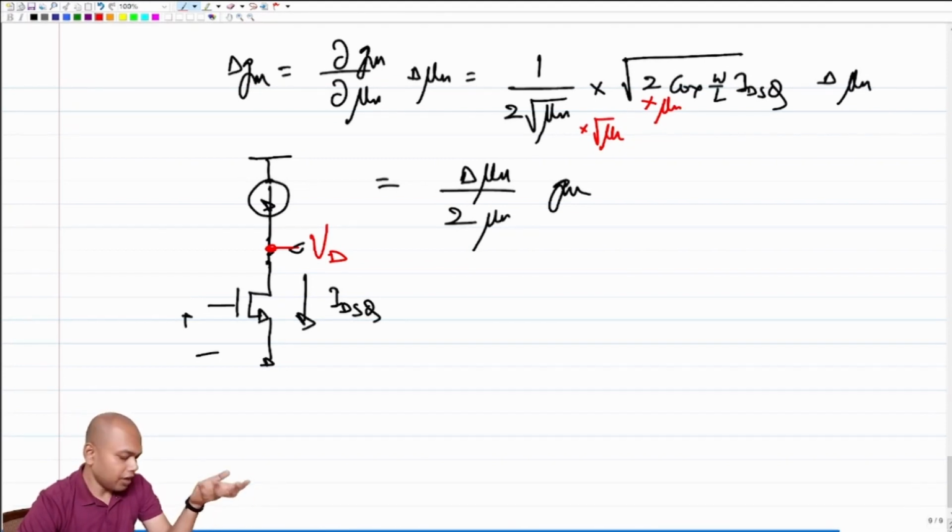One might say that if the voltage between the gate and the source of the transistor itself is undefined, how can you ask me to make a comment on the voltage between the drain and the source? And that is a right assertion to make. There is no way we can tell what will be the voltage at the drain. So if we cannot tell the voltage at the gate and at the drain, we also cannot tell the operating condition of the transistor.